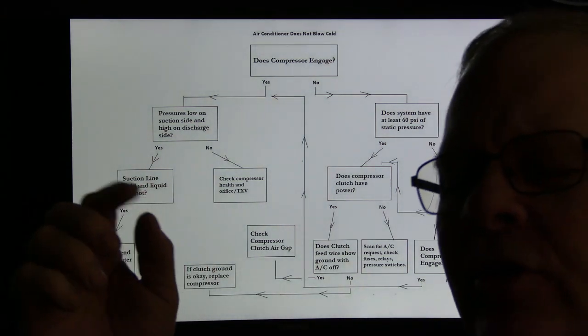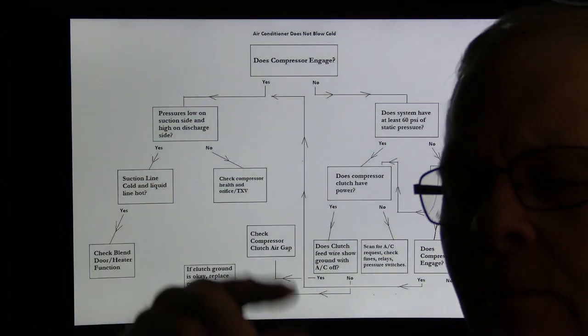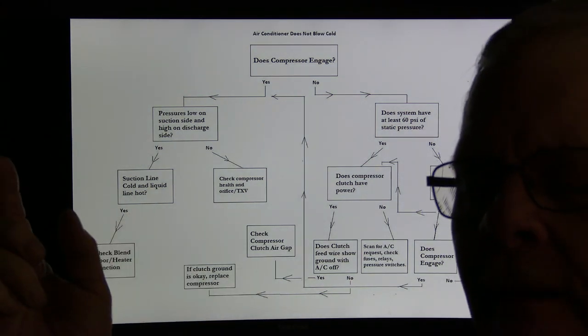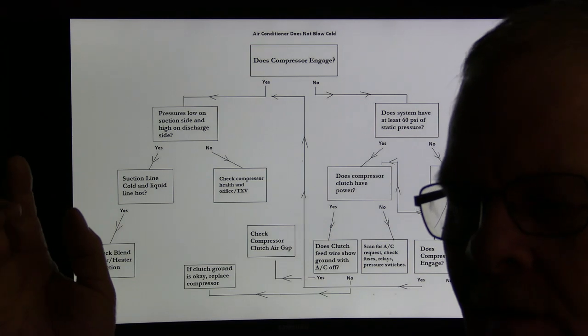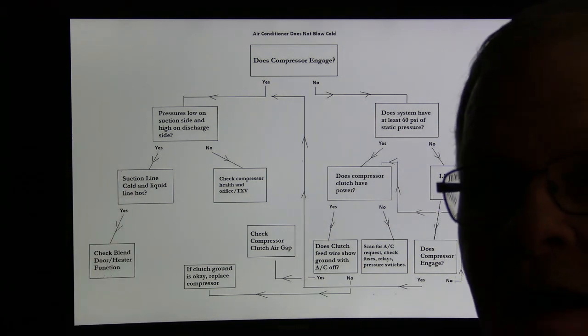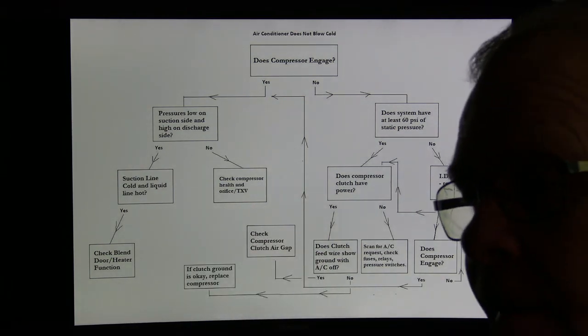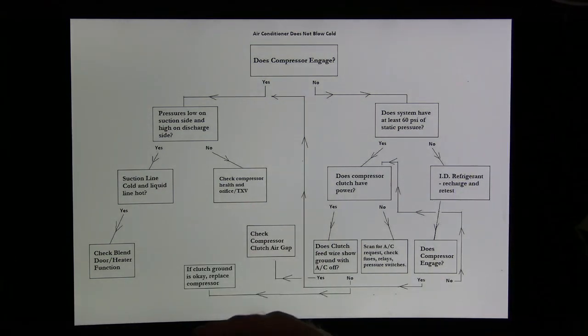Occasionally, one time on an older Toyota Camry, we put an expansion valve on it for pressures that were low across the board, and the expansion valve didn't fix it. We had to put an evaporator on it to fix it. That fixed it, which was weird because the evaporator didn't appear to be stopped up. I could blow air through it.